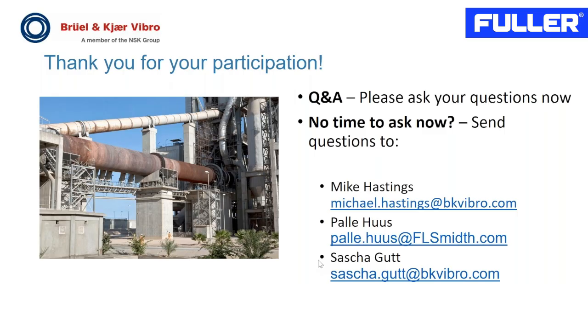Yes, I can elaborate on that. We have selected some measurements or failure modes that are well known, so we have well-known limits for these types of measurements. That means we can do active monitoring simply based on threshold limits. Additionally, we use some calculation models to detect behavior in the signals, such as automatically identifying a cycle or automatically identifying maximum and minimum values.